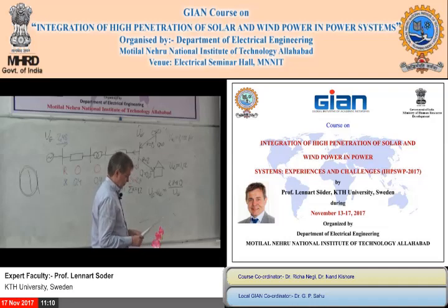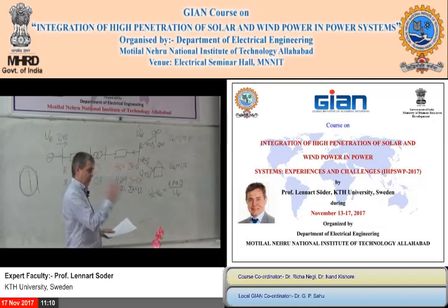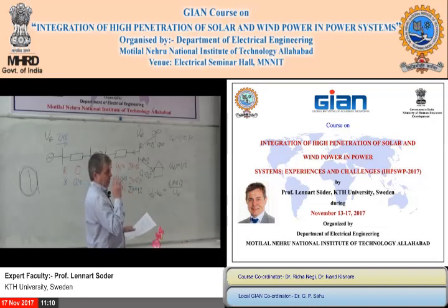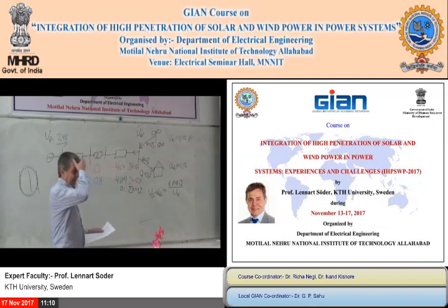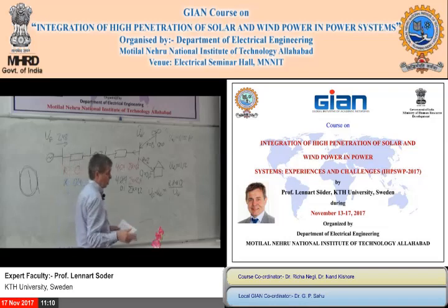Part 2: why does inertia become an important challenge? The reason is this extremely fast response. Exactly when something happens in the system, the initial balancing in the system is the inertia. And that comes, in conventional power systems, in all power systems, mainly from synchronous machines. Then you have a small contribution from asynchronous induction machines, also from motors.